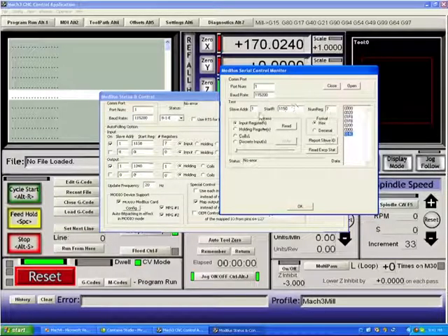You can test it simply by setting its slave address, setting the start address that you're going to read from. Each ModBus device has a different start address for the data that you read from it. And each one will have a different number of registers that you read. Some people, for example, would only read one register from a ModBus device for the particular use they're going to put it to. As you can see, when I hit the read button, we read the 7 registers successfully, and that means we do have communications at 115 kilobaud with Peter's board.